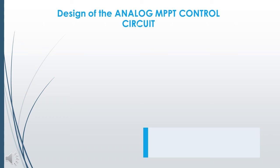Below are some of the most important layout rules of CMOS transistor matching. Locate the transistors in the same direction and as near as possible. Both the parallel transistors and the near transistors assist in reducing transconductance variations. Use the same fingers for all the matched transistors. Use dummy gates to reduce the effects of etching. Use common centroid design techniques. The matched transistors should also be separated into an even number of fingers and arranged symmetrically. Once circuit specifications are fulfilled in simulation, the circuit layout is created using the Virtuoso Layout Editor.